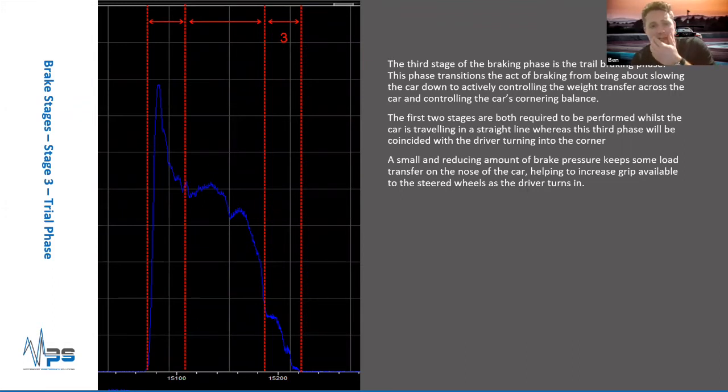The first two phases were about the main priority of slowing down the car, whereas as we reach the third phase, it's much less about slowing down the car and actually controlling the load transfer across the car. So we're using significantly less brake pressure than we did earlier in the corner. All that's doing is making sure the driver has control of keeping load slightly on the front. We do this because obviously the wheels steer, so the more load, to a point, obviously there are trade-offs, the more load we can keep on the front of the car, the more steering, cornering grip we get.